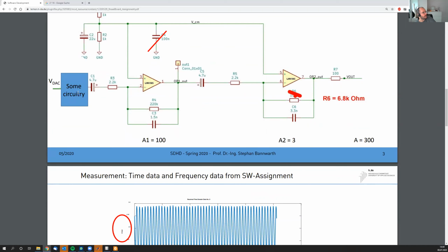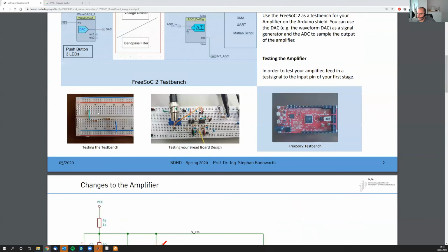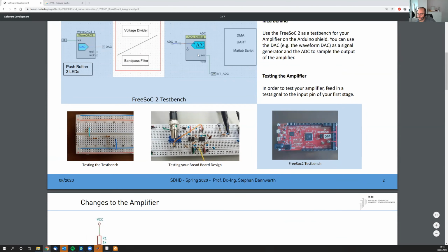I mean, what you could do, I'm trying not to overcomplicate that, but you could verify that if you first understood that calibration run, right? Where I said, you simply connect your output directly to the input, and with that you can calibrate your ADC. Then you know exactly what is going on.